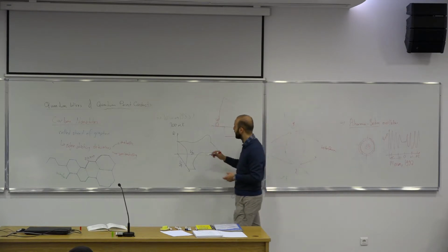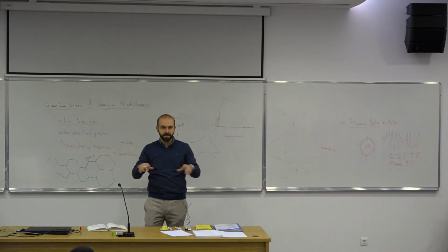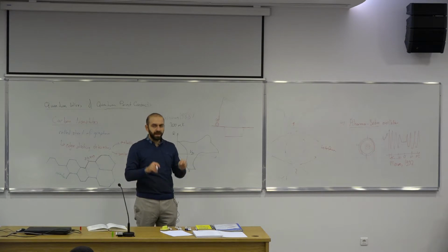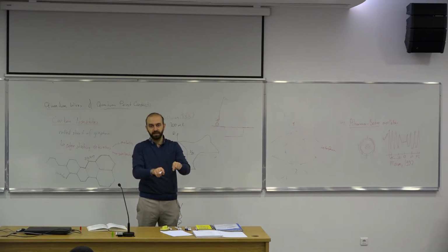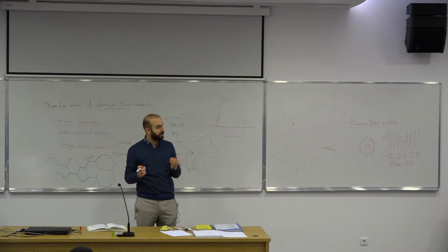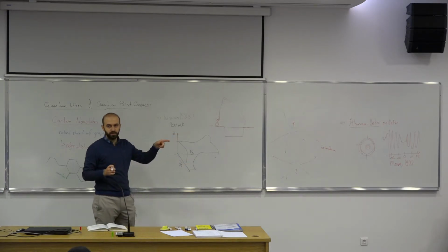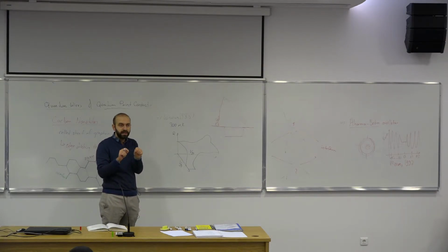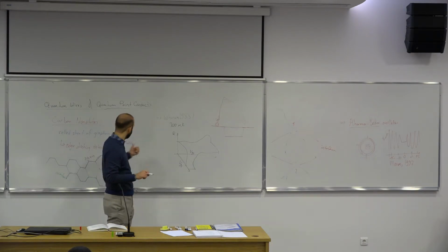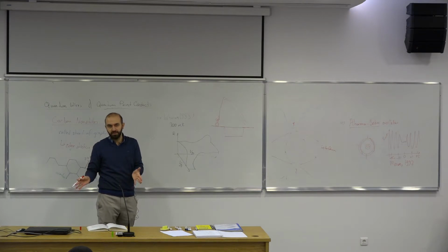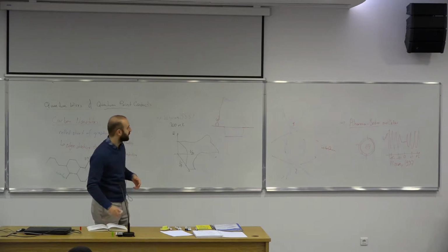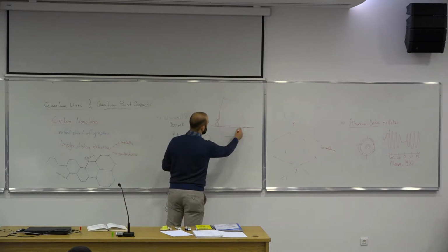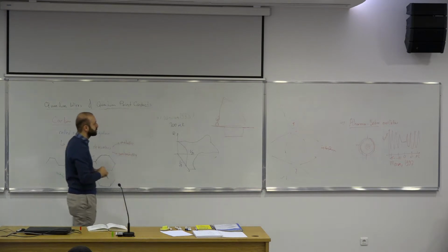And they literally had hundreds of devices on a single chip. They would measure every single contact to see if there is a carbon nanotube crossing. If they have a metallic carbon nanotube, they adjusted the amount of bias in such a way that they would burn the metallic nanotube because of the too high current passing. But if it is a semiconducting one, then it wouldn't burn. So with that, they could get rid of metallic carbon nanotubes. Also, there could be multiple crossings, like one metallic, one semiconducting, and so on.